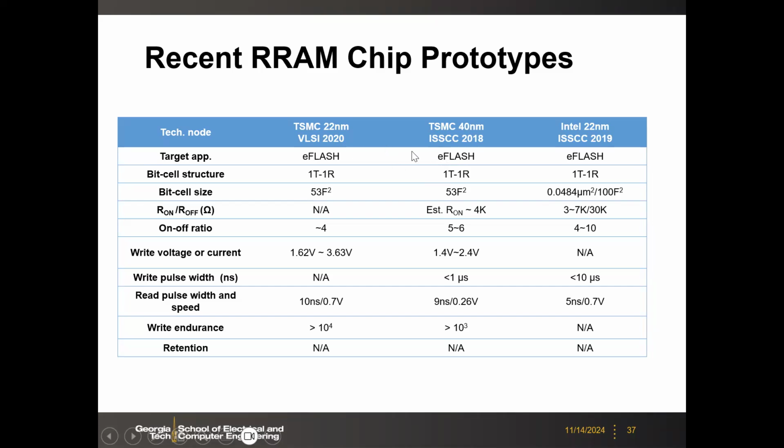So that's why industry wants to have the RRAM, and later MRAM, with similar targets, to extend the embedded non-volatile memory beyond 28 nanometer. For let's say 22 nanometer, even 16, 14, 12 nanometer, even 7 nanometer on the roadmap, to have the non-volatile memory option for embedded applications, especially for the MCU.